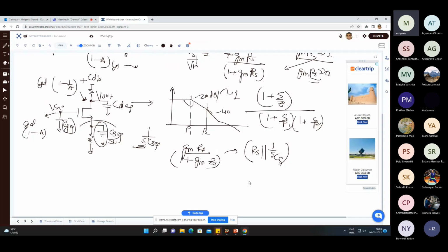We will discuss that. Remember, we had discussed the concept of equalization, where we intentionally introduce a high pass kind of characteristic so that the channel's low pass characteristic multiplied by the high pass characteristic of the receiving amplifier gives a flatter response. So generally in the receiving amplifier, people add this additional capacitance at the source so that this kind of high pass behavior can be obtained.